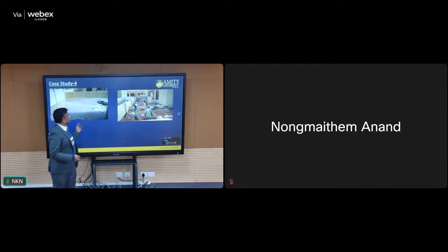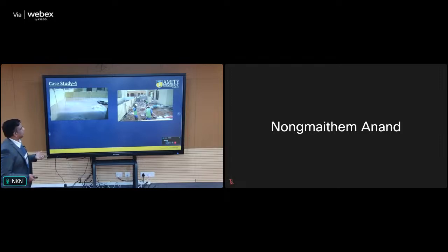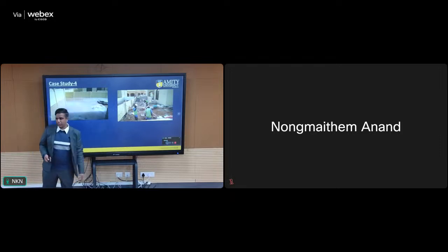After doing that, again we flooded this with water, and we identified that the soil which was responding to the entry of water is not giving that much response now. So that is one of the techniques that we have proposed, and they have implemented it in this particular project.